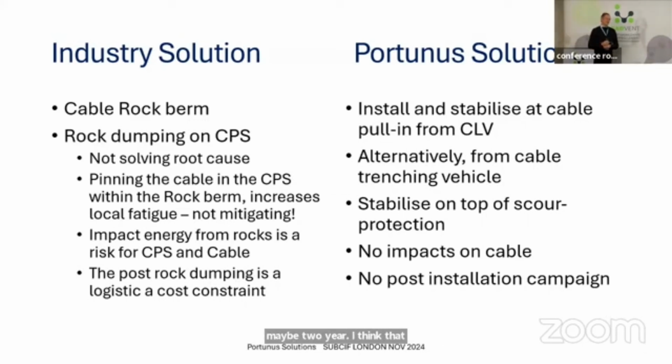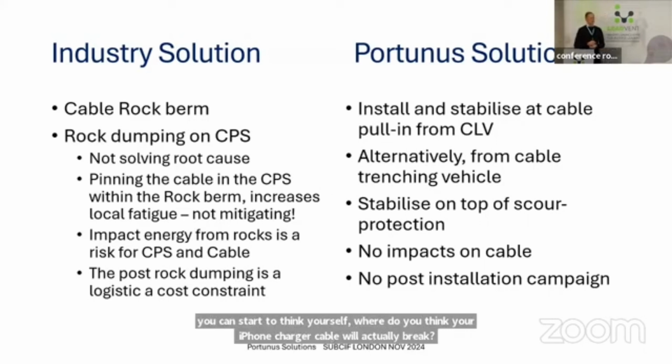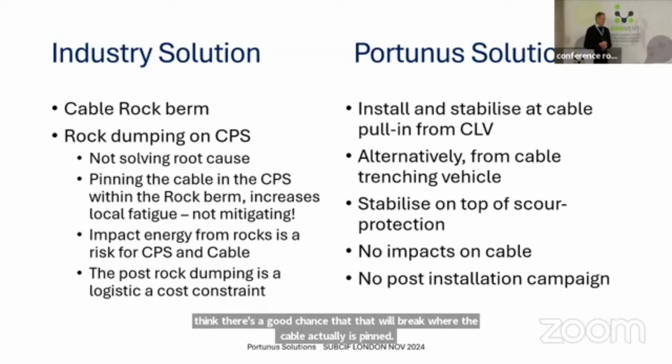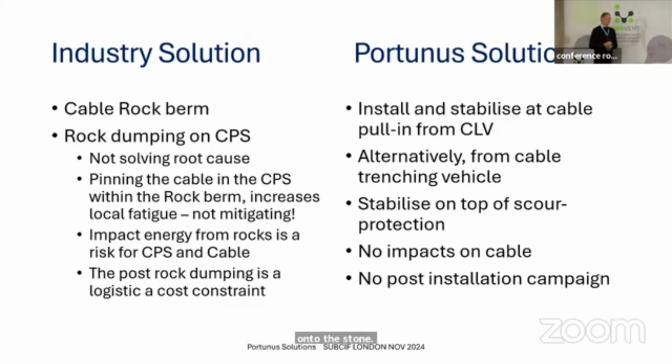And you can start to think yourself, where do you think your iPhone charger cable will actually break? I think there's a good chance that it will break where the cable is pinned under the stone. And that's exactly what's going to happen with your offshore cable. You will focus all the fatigue at that point where you pin it under the 17 tons of stone.